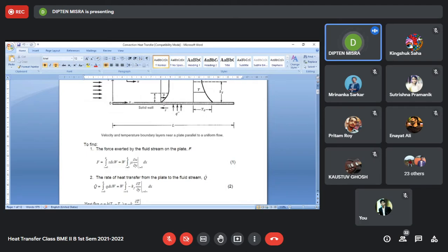So the only way the heat is transferred from the wall into the depth of this zone is across the sticking layer of fluid. There is one layer of fluid sticking on the wall, and the heat passes from the wall to the moving fluid via that sticking fluid layer. So the mechanism of heat transfer in the sticking fluid layer will be by conduction.